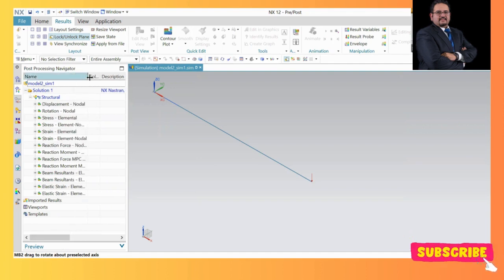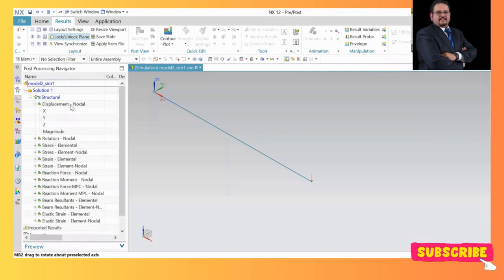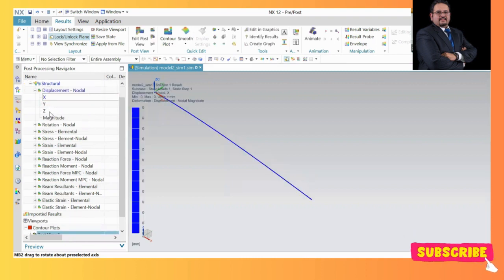For example, if I talk about nodal displacement, you have three displacements coming, right? If I press Z, do you see any displacement? No, right? Because if the force is applied only in Z, the deflection is also only in Z. You don't have X and Y deflection. If the load is in Z, it will only show you values in Z. So here you can see the magnitude.